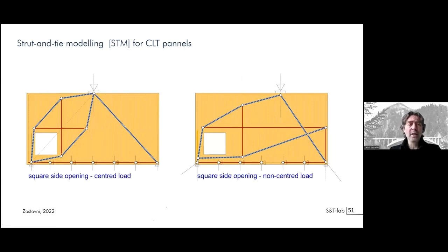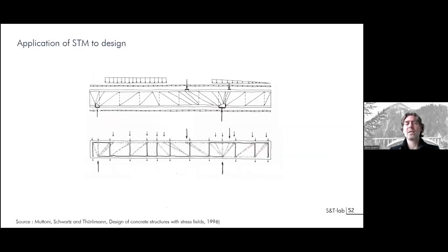And with this, you can analyze quite complex systems for which we have no simple mechanism coming from the classical approaches from the elastic theory. So this application is developing a system of strut-and-ties. This is an application of the lower bound theorem, the static theorem of plastic design. So we are projecting a system into it for the analysis, and that makes all this interesting.